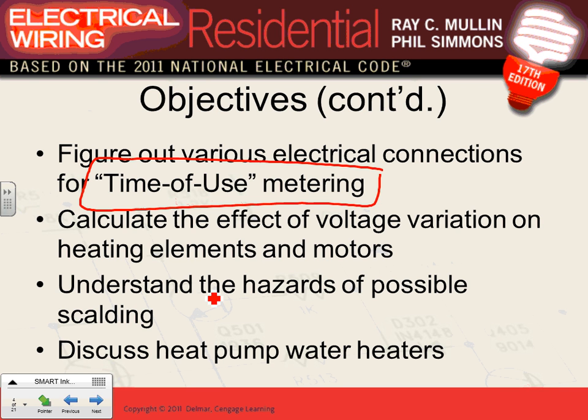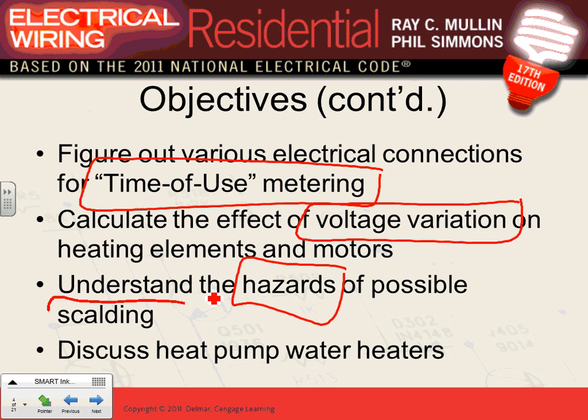We'll talk about these. Voltage variation. What's the acceptable voltage? When we say 240, Aaron, you rarely will ever measure a voltage and find a 240 in a house. So there's plus or minus, as we always say, 10% acceptable range for water heaters and motors. I'm not going to touch too much on scalding. If the water is so hot, protection from scalding and all this good stuff, that's basically part of the water heater control system that they have.